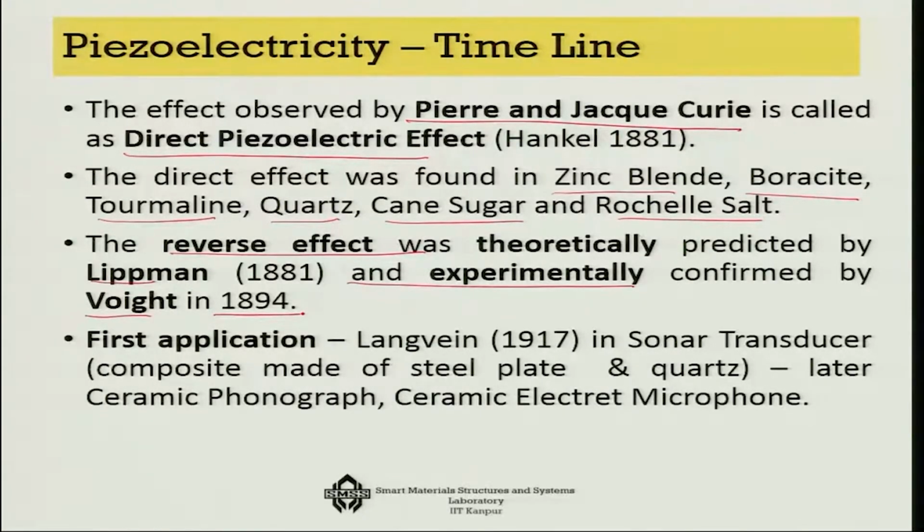However, the engineering application took some more time, at least 30 to 40 years, when Langevin used this principle in order to develop a sonar transducer. This sonar transducer is actually made of a composite of steel plate and quartz. So suppose you have a steel plate and you have a quartz at the center, and then you apply voltage to this quartz. So you are applying voltage at a particular frequency.